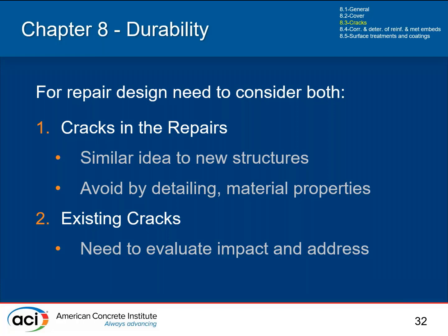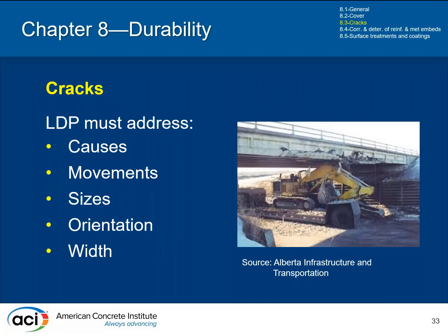So you're looking at a big spall and you've got a crack in your spall. You don't need to worry about that, because the first thing you're going to be doing is demoing out that spall and all the cracks that are associated with it. But you really need to evaluate the impact of the cracks that will likely remain. Is this something that we can deal with that will not have an impact? Or if it is going to have an impact, what do we do? So when you're thinking about these types of cracks, I'm going to talk mostly, in this section, about the cracks that remain, because you should all be familiar with avoiding cracks in the new portion of it.